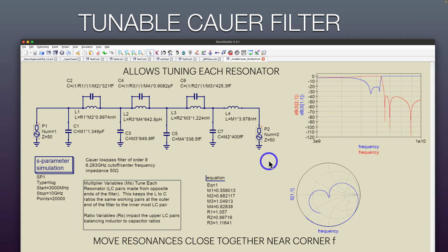However, you can add in tuning elements where you still say, well, the first components are combined with the last components can be scaled, and then that moves resonances around. I can do that for any combination here where I look at these components matched with that C, this component matched with this C for the highest frequency is the center section. And so all of these can be tunable to be able to tune the main frequency that you care about. So we say we don't care about these lower frequencies, but we do care about the band that we're working in. And then we also care about trying to block high frequency signals.